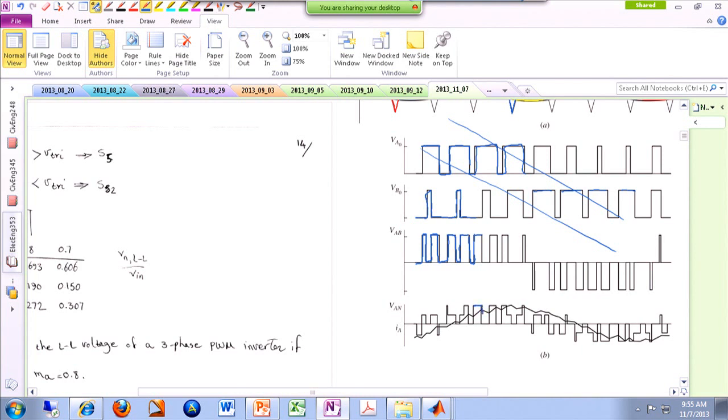This is the line to neutral voltage of this PWM bipolar switching scheme for phase A. Then you can divide this voltage waveform by your impedance, or do some circuit analysis, and find your current waveform, depending on what kind of load you have. Most of the time your load is a resistor in series with an inductor.